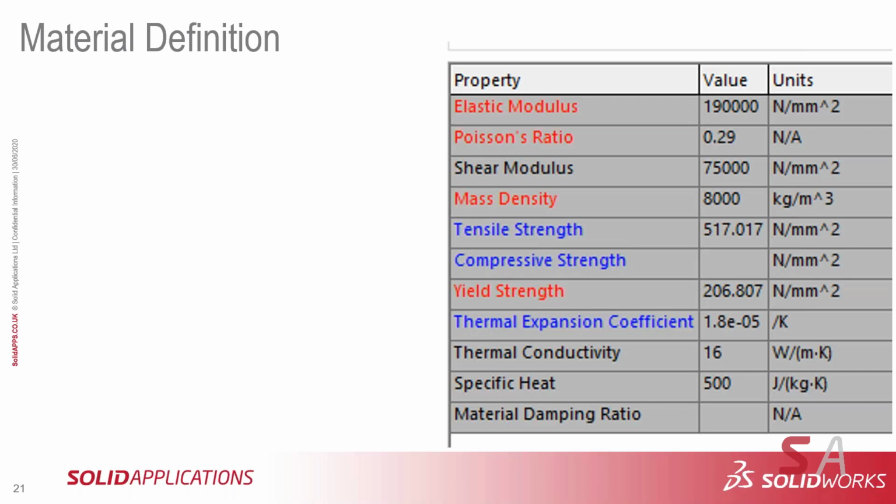So for example, a lot of times the modulus of elasticity for a lot of similar materials is very similar, if not identical. And the Poisson's ratio is usually similar. Steels usually range between 0.29 and about 0.31. Most of them are just under 0.3. Elastic modulus for most standard steels will be somewhere about 190,000 to maybe 220,000 for simple carbon steels. On the other hand, a high strength alloy steel will be like 620,000. Excuse me, that's the yield strength.